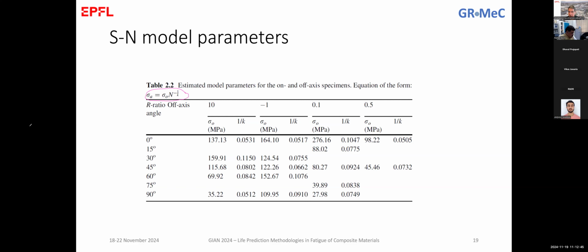So you see that even today we use the same equations like Basquin did 110 years ago. And these equations are still valid today, because as we discussed yesterday, they are valid for more or less any material. You can also use this equation for metals fatigue. Although there the standards are simplifying, and you usually take a linear plot, but again, it's a linear plot in a logarithmic scale. So metals are using the same equations here.